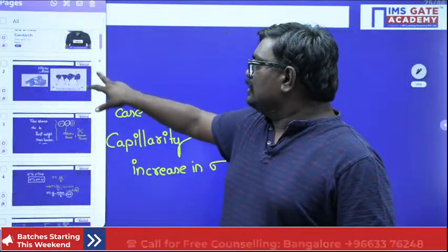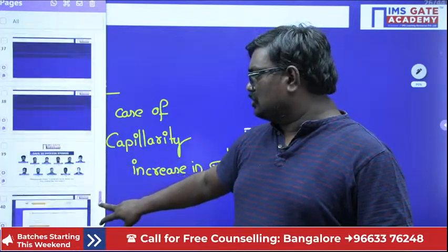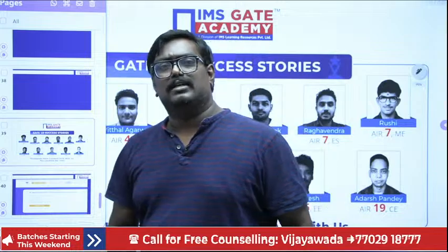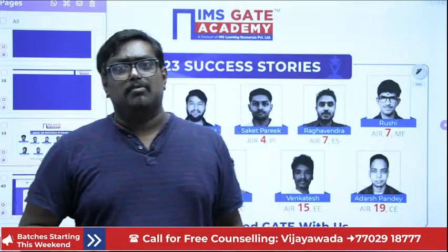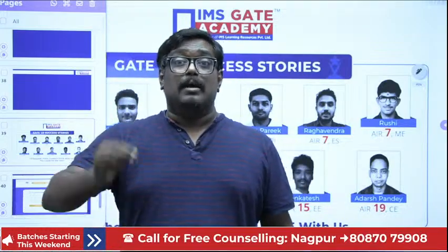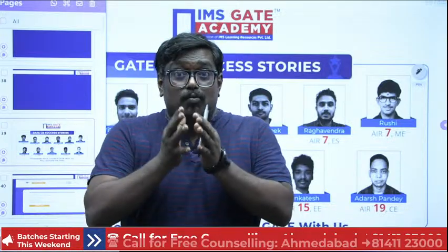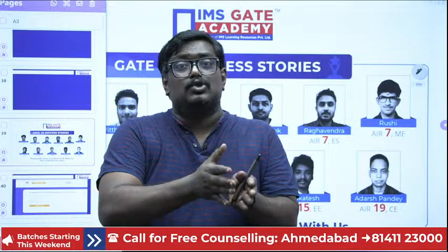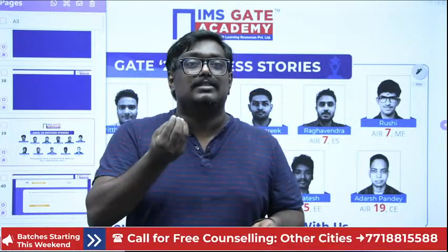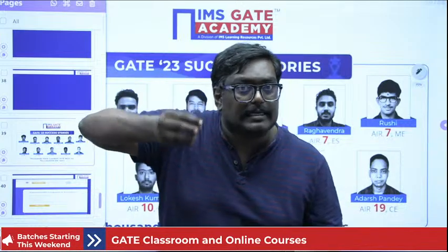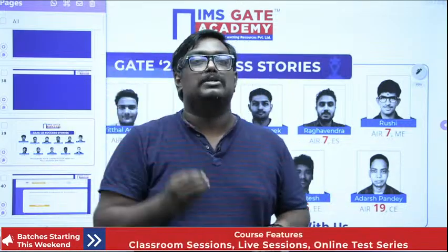I hope you have enjoyed the effective stress concept, students. The basic agenda of effective stress is as simple as that. You should understand why you are learning effective stress, because the shear strength is a function of effective stress. Why do you want to study effective stress? To know the shear strength. Based on the shear strength, we can judge whether the soil is loose or dense. And the settlement also depends on the effective stress.